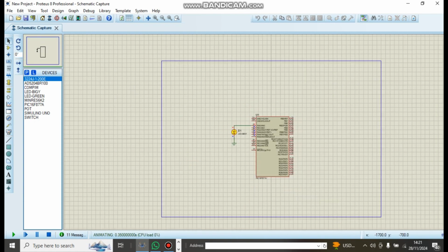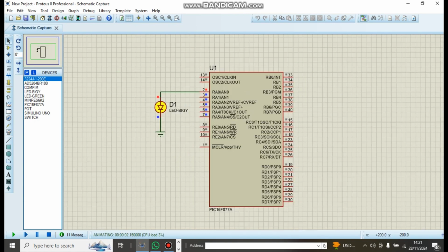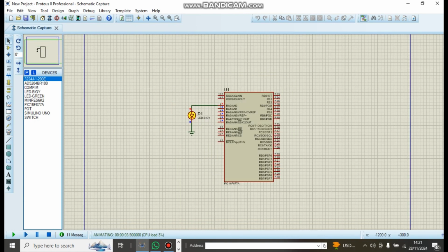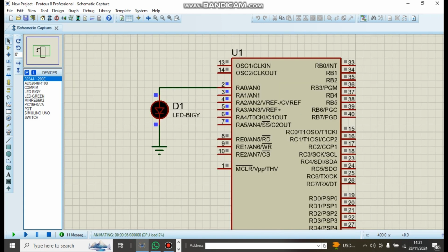So if we run this code, just as expected, the LED goes on and off repeatedly forever. So it goes on, waits a while, goes off, waits a while, goes on, waits a while, but doesn't affect the states of these pins at the bottom. Pins will remain as 0 the whole time. See the blue color here shows that they are off. The alternating red and green, and red and blue shows that it's turning on and off periodically. These ones are not being affected.